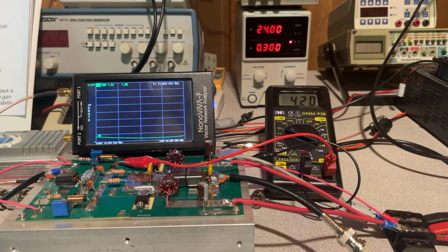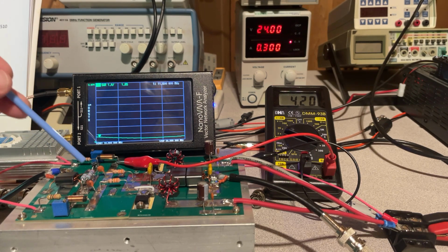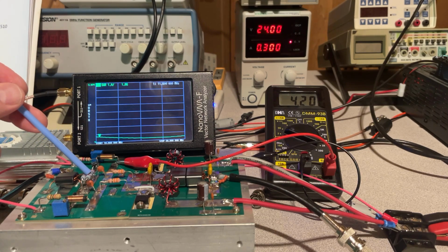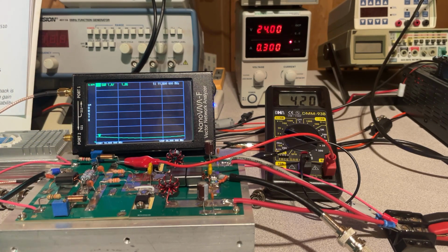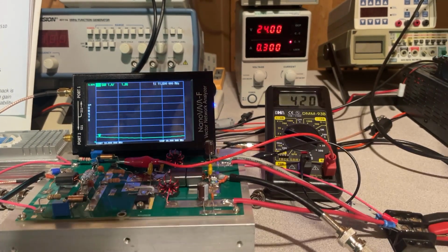And we talked about why we add this resistor across the output of the transformer, right? We're calling this a Q dampening resistor, right? So again, it's the ratio of the impedance of the transformer and the resistance, right? So we basically increase or decrease the Q with this resistance value. And what we want to do here is reduce the Q to increase the bandwidth. So what will happen if we go ahead and lift that resistor? Just to give you a quick demonstration on what the results would be.